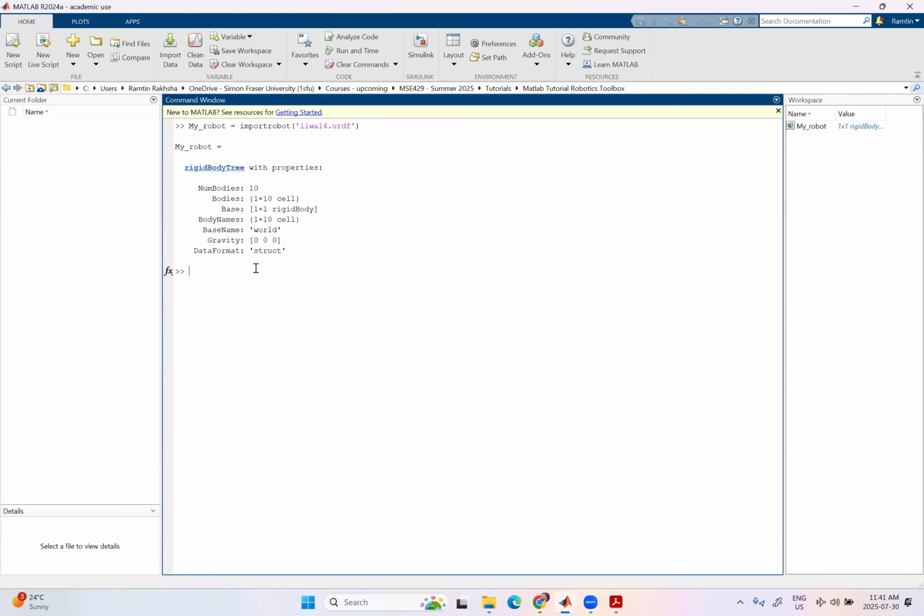Once you do that, there is another step that we need to do, which is basically the Simscape import, because things are now imported to MATLAB, but now we would want to load it in Simulink in an environment that does dynamic simulations for us, okay? Because let's not forget, in Simulink, what it does is solve a bunch of differential equations for us with whatever numerical technique it has. There is no physical interpretation behind any signal that we define. So you grab a scope, say, okay, sine signal. Then I think it's voltage, but technically it's not. MATLAB doesn't know that, right?